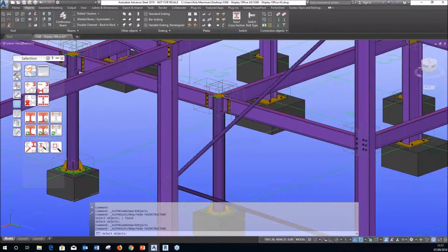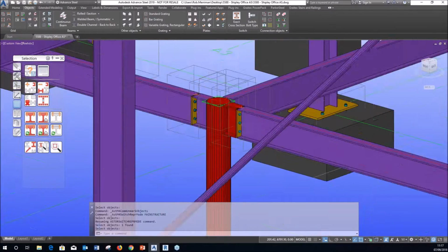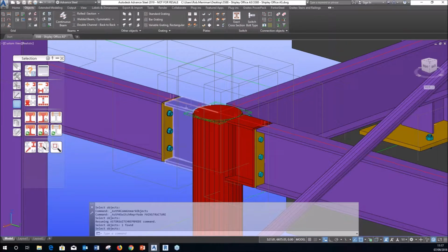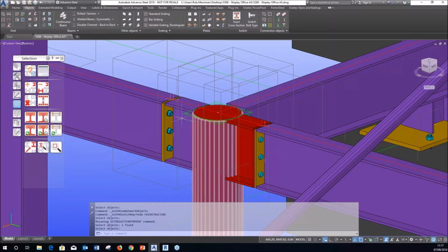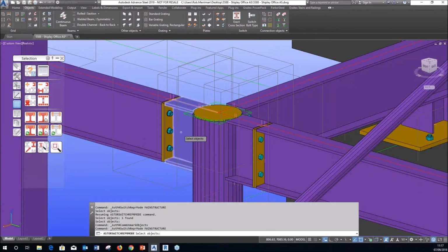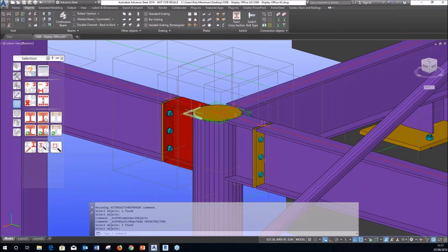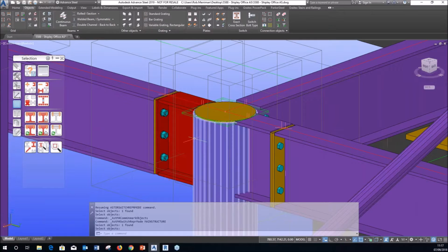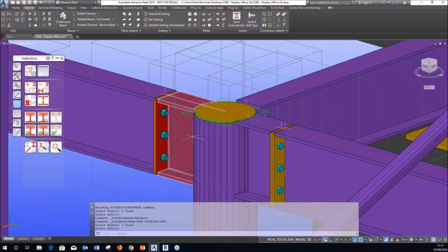What I'm interested in here is the stuff that you do manually. So the items that I created manually are this assembly here. And we can actually see that in this first one, I've forgotten to weld the haunch piece to the column. The end plate, if I clear the marking, is attached to the stub section, which I expect it to be because it's done with a joint. But that stub section, it was my responsibility to manually weld it to the column.